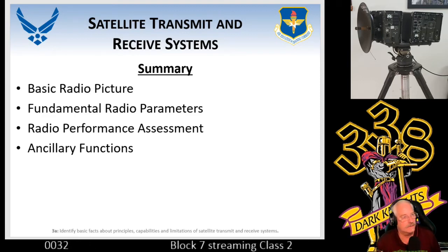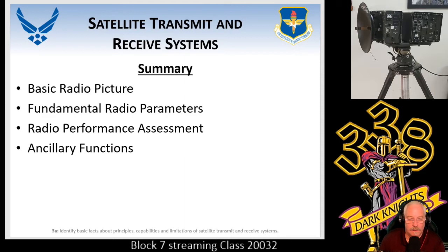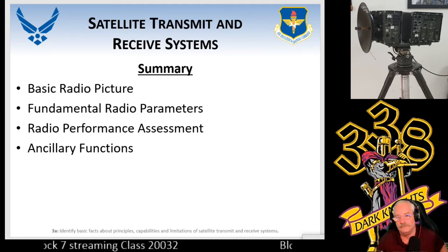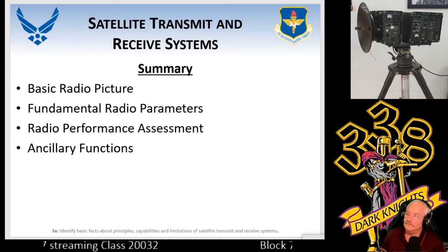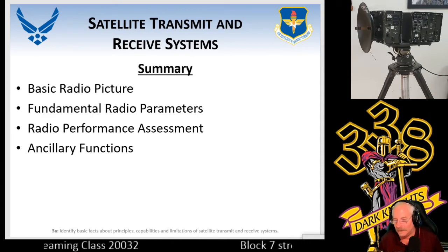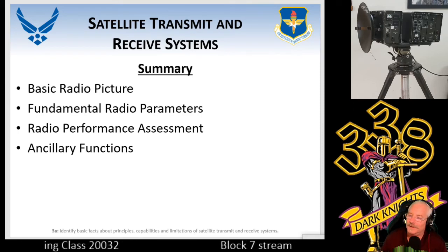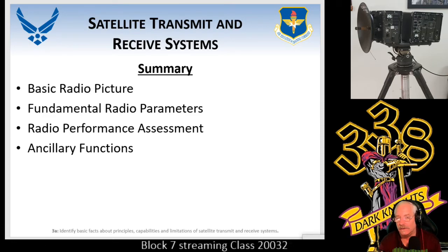Excellent. Alvarez, do you know what the 3 steps are for it? I don't, sir. Okay. Do you know, Bakken? Are you talking about the multiplexing, modulation, and then amplification? Yeah, but the first one isn't multiplexing. It's actually modulation. We're taking the multiplexer, the aggregate, and we're modulating it to an IF signal.